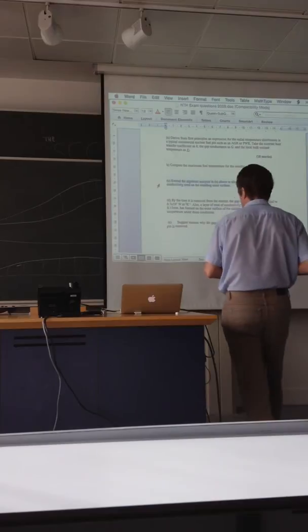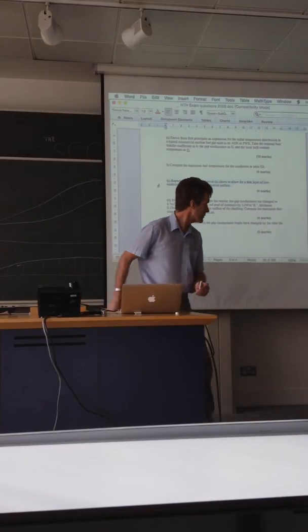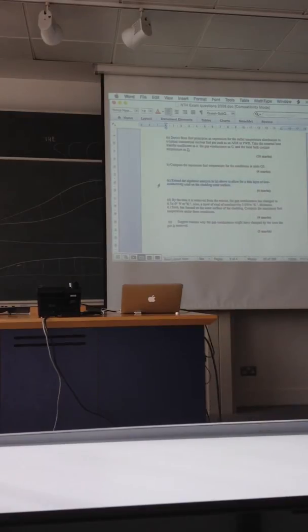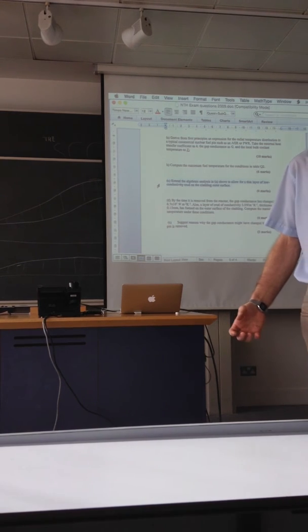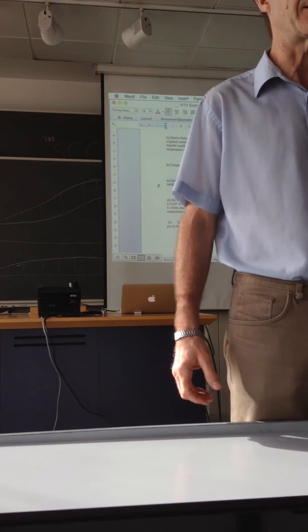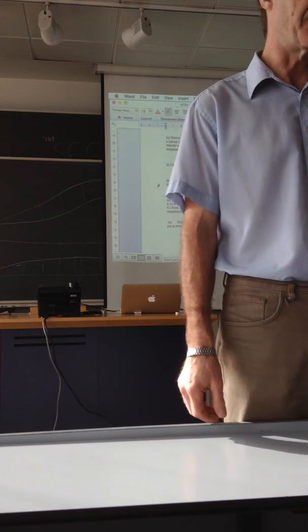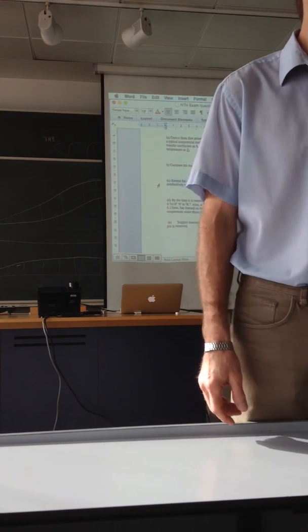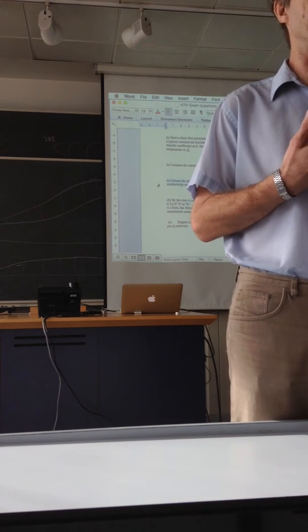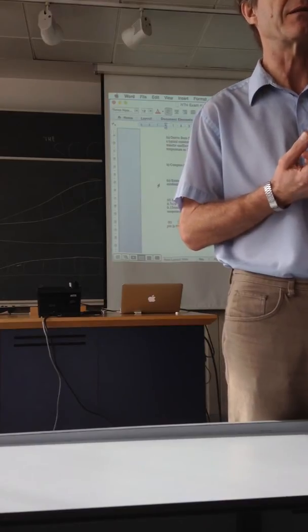So is that what you mean by a constitutive relationship? What does it mean? A closure relationship or a constitutive relationship. It's Hooke's law: sigma equals Young's modulus times strain. That would be a constitutive relationship. Or shear stress is some viscosity times du by dy for a fluid flow. That's a constitutive relationship. It's telling us something about the behaviour of a material, broadly, is what it means.